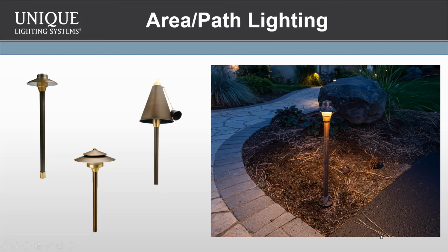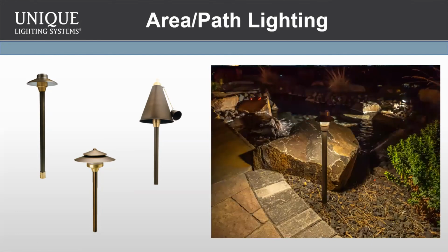Or if you get a chance, somehow protect it with a boulder or some sort of plant material, so that way it's a little bit out of the way. I will say that I will do my hardest to prevent putting path lights in turf. At that point, they don't last. They definitely get hit by line trimmers. They get knocked over by mowers. They never really look good.